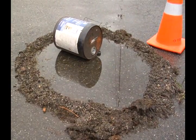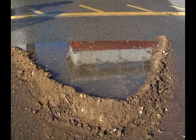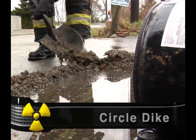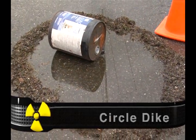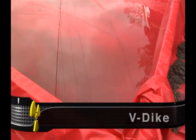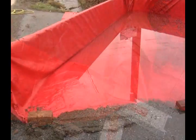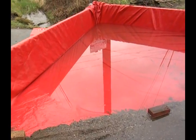There are two common dike shapes, the circle dike and the V-dike. The circle dike completely encloses the material. It is usually used with slow-moving materials. The V-dike is used for faster-moving products when there is not enough time to completely enclose the spill. Be sure the walls of the V-dike are long enough to hold the product within the confinement area.